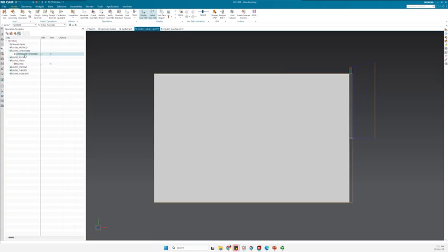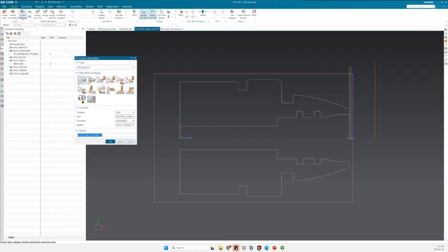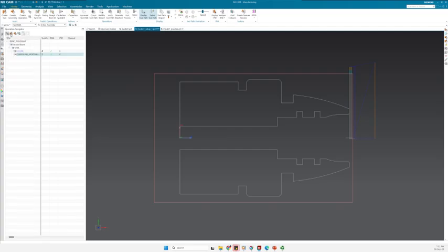We can also check it out from the operation or machining method view. All right, I go to the next operation, and this is the drill. I go to the drill. So as we confirmed and we agreed, we're gonna do only one drill and only one diameter of 20. But as you remember, we have not defined the drill yet. So I go here to the list of my tools. I can see that there is no drill, and then station number 4 is open.